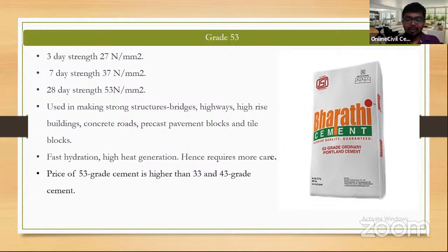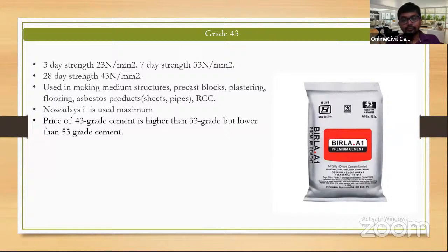And even if you are using this, proper curing should be ensured. If it is in a column, proper curing even after the casting, one day after casting, should be done with the help of gunny bags. So this you can do, and the price is obviously higher. We'll also move on to a price comparison later on.